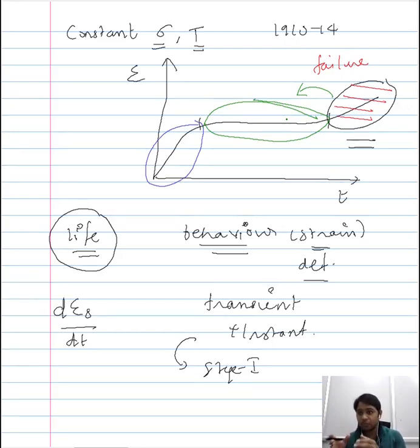So once you experience an accelerated creep, or once the material begins to deform in an accelerated manner or begins to exhibit a high amount of creep or high amount of strain, the creep test is stopped, and then the focus is rendered to the strain exhibited by the material in stage 1 and the life of the material in terms of stage 2. So to put it simply, the creep test will not be carried on till the material fails. The creep test will be stopped once the material begins to deform excessively, meaning once the material gets into the third stage of the creep curve, the creep test is stopped.